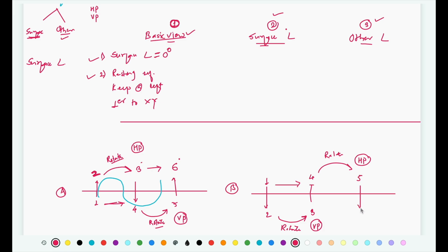Then project it vertically downward, project it horizontally, and draw step number 6. So in the second scenario, the flow of solution is going to be like this. Okay, so in both cases we are going to follow a zigzag path, whether you are starting with front view or starting with top view. So out of those two scenarios, any scenario could be applicable to a given example.